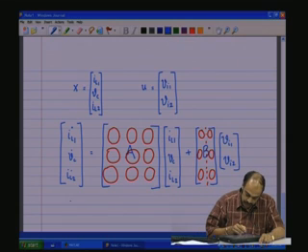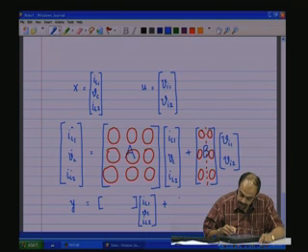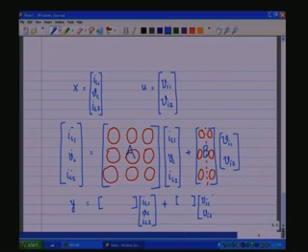and the output y, whatever the output y is supposed to be, will contain the C matrix, IL1, Vc, IL2, plus we have Vi1, Vi2, and as there are no direct feed forward terms, that is 0 and 0, and here if it is Vc that we want to consider as an output variable, then it would be this 0 1 0.